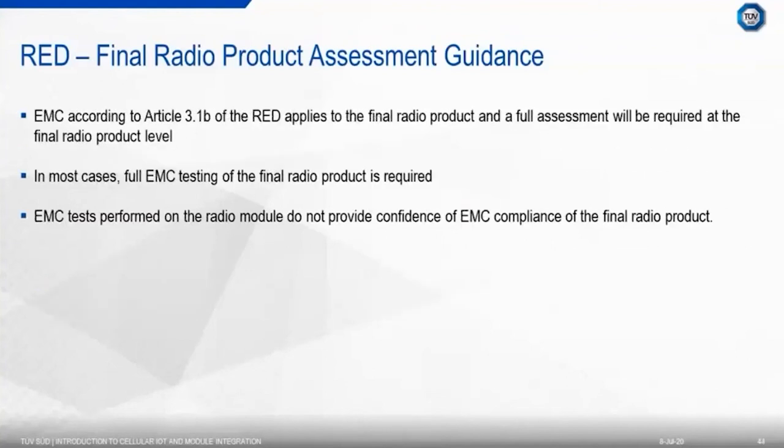EMC testing under Article 3.1b of the RED will apply at final radio product level, which in most cases means full EMC testing, because EMC tests on a radio module don't provide confidence of EMC compliance at final radio product level.